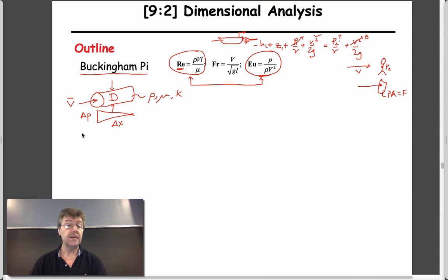And those are pretty much the behaviors that we would define this. We know from talking about the Navier-Stokes equations and the energy equation, the most complicated form, that what comes out is that the average velocity is related to the diameter squared, over 32 times the viscosity of the fluid that's flowing, times the pressure gradient across the length of this.